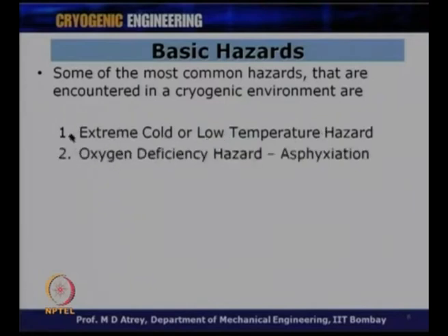Then, one most critical basic hazard related to cryogenics is that it can produce an oxygen deficiency hazard. It can produce an environment where we have oxygen deficiency, and this is called, in technical terms, asphyxiation. So, asphyxiation is a condition in which you have an oxygen deficient environment around you, and this is very, very damaging for human beings. So, this aspect is very important to be dealt with when you are dealing with cryogens or cryogenic gases. Then, on the contrary, you may have the opposite one also, which is the oxygen enrichment hazard. You can have a situation where the environment around you has more oxygen than required, and it can lead to other hazards which we will understand during this lecture.